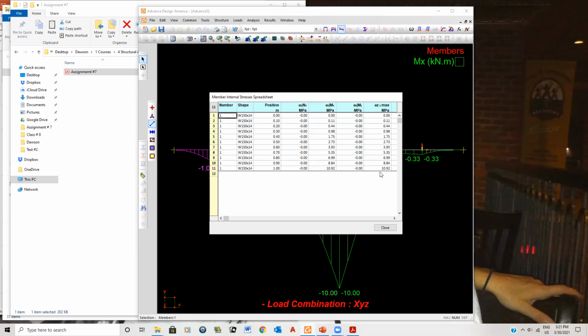I'm glad you asked me that question. As far as the analysis goes for forces, it's exactly the same value. But at the same time, if you ask the program to design, it would limit itself on that strength of steel to be able to select the member. That's the other difference.